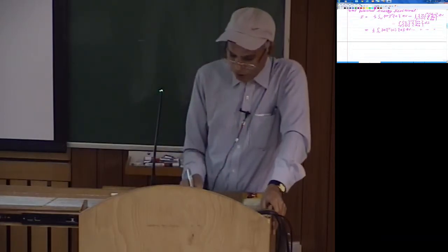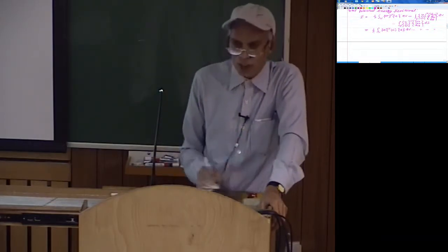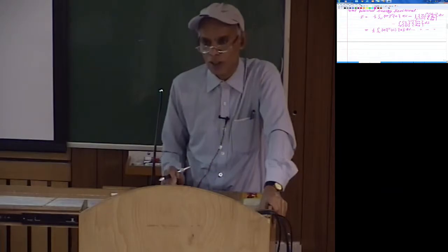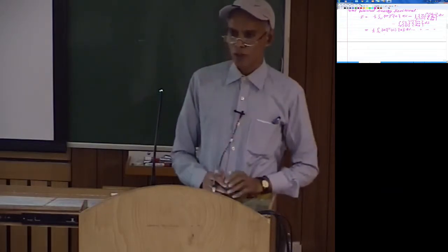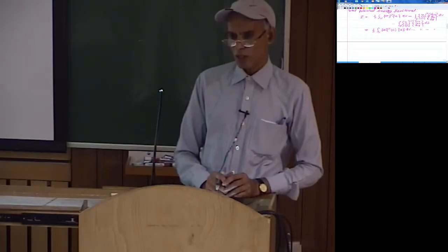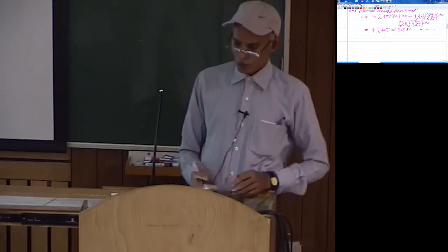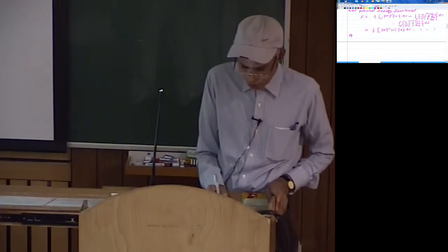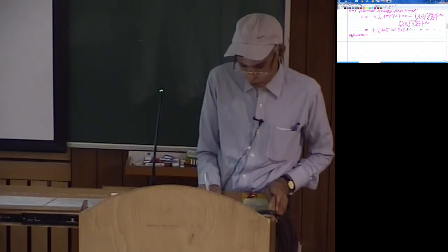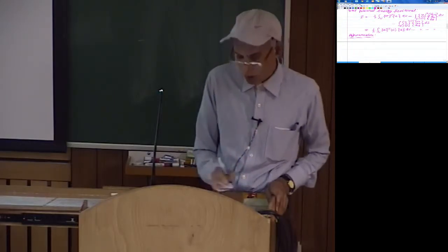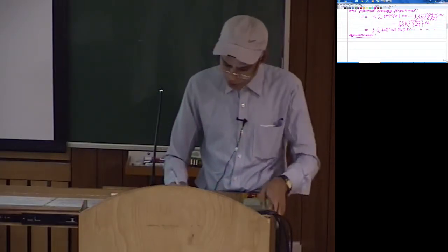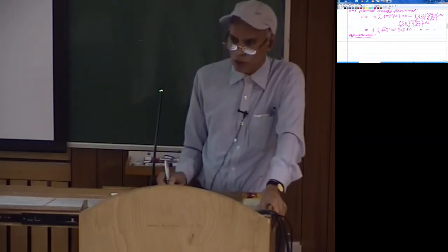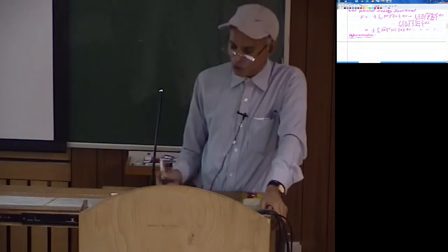Now if you look at the interpolation, epsilon is in terms of first derivatives of the displacements with respect to x, y and z. So whatever solution we assume should be differentiable at least once with respect to x, y and z. Within the elements, since the highest order derivatives of the displacements, which are unknowns present in the integral functional, are first derivatives, whatever we assume must be differentiable at least once.